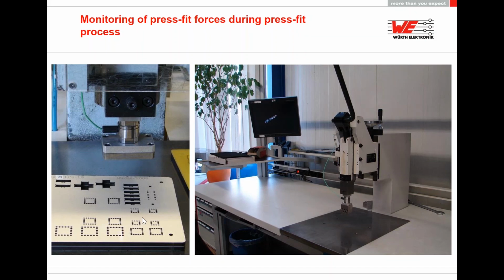Even aluminium is too soft. So you should use something like steel that is not deforming over the period of many press-fit processes. If you have a few thousand press-fit processes, it can deform because you generate some force through the PCB over thousands of cycles. I guess that's it.